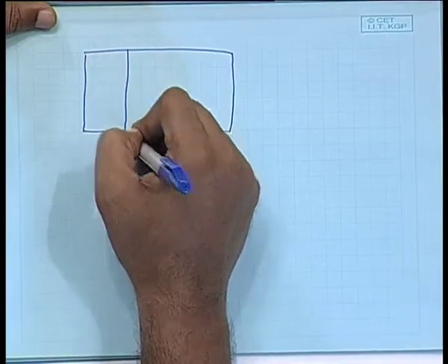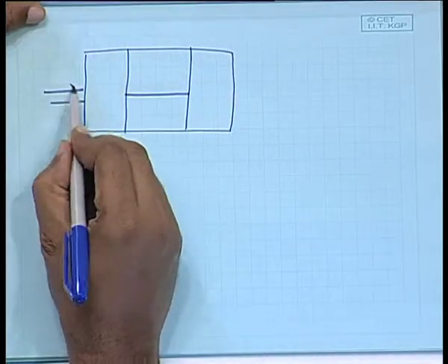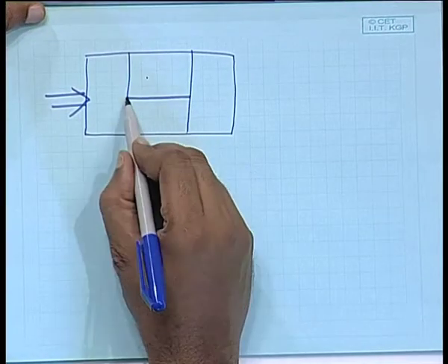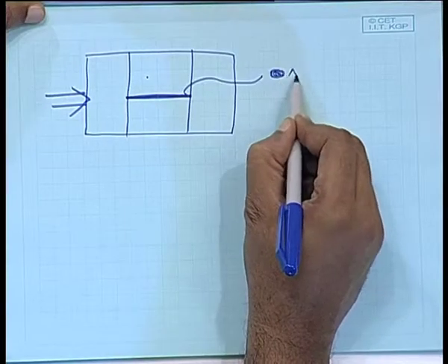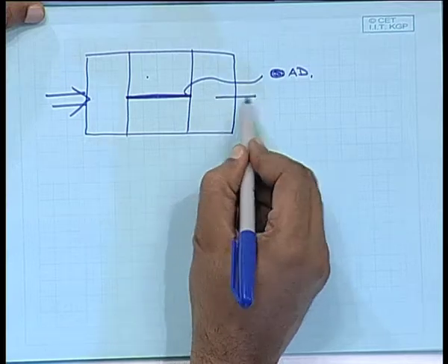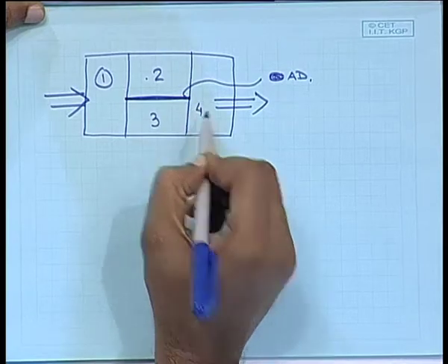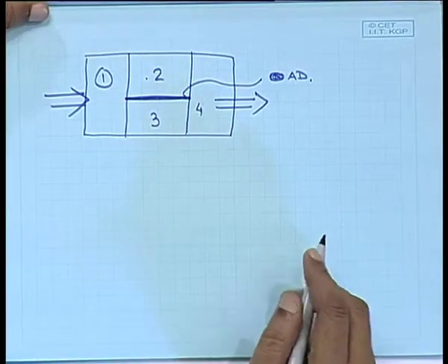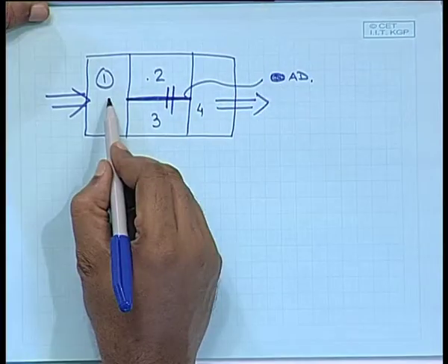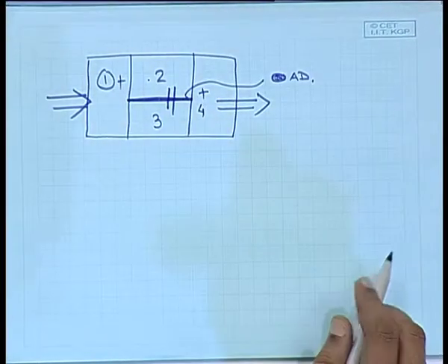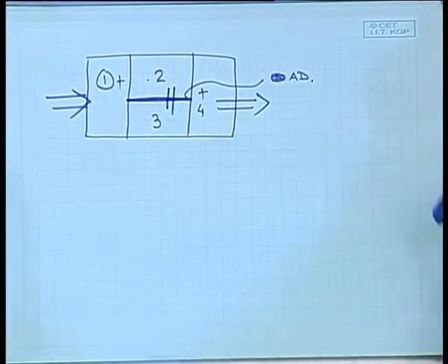These are more of academic interest, I would say: you have a wall where heat is coming in, a different wall, but this is insulated, or I would say this is an adiabatic surface, and then you are going to have the heat outside. So, you have resistance 1, 2, 3 and 4. Now, what would be the circuit diagram for this? Okay. So, 2 and 3 are parallel and these are in series. This kind of simple geometrical thing you would be able to know. I do not need to spend any time on that.